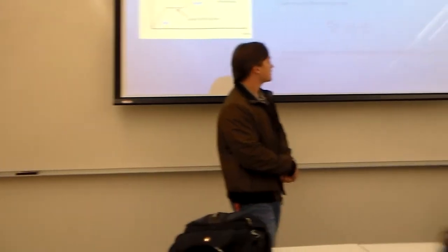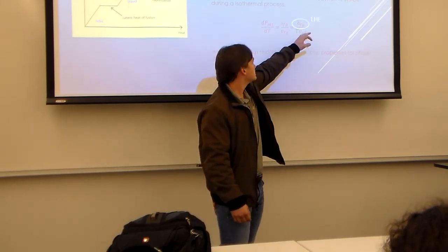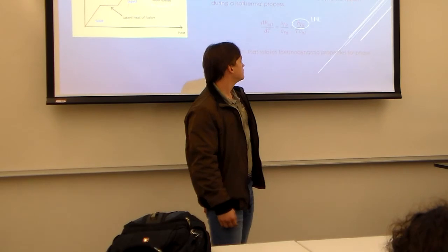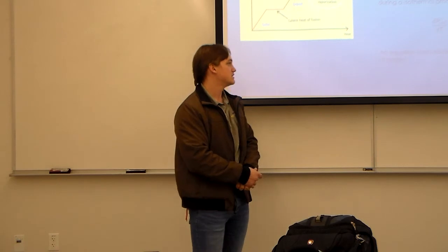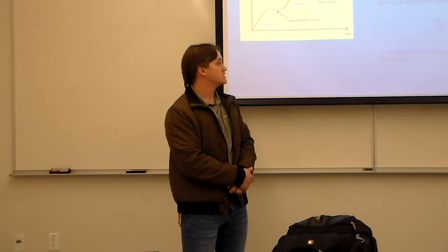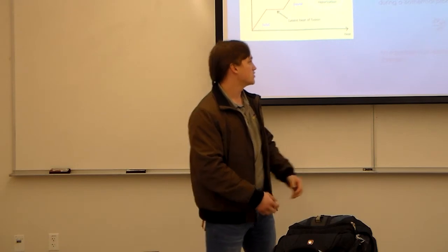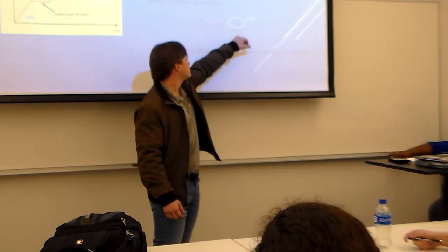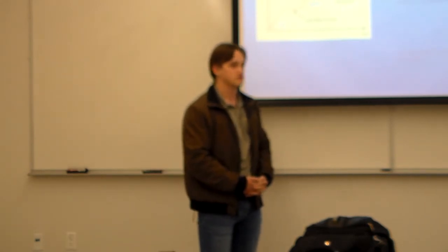This is the Clapeyron equation right here. This is the latent heat of evaporation term, h_fg, and it's basically an equation that relates the properties of the thermodynamic system. Right? So things like your pressure and your temperature and your specific volume, they can all be related in this equation. You can also use the ideal gas equation as well, since it is in a vapor state.